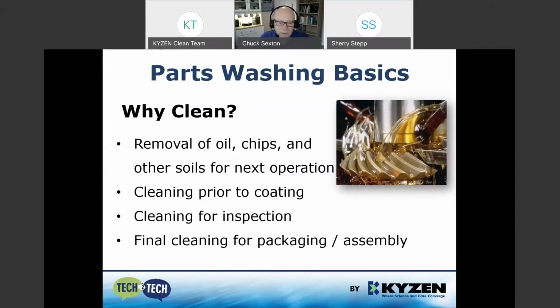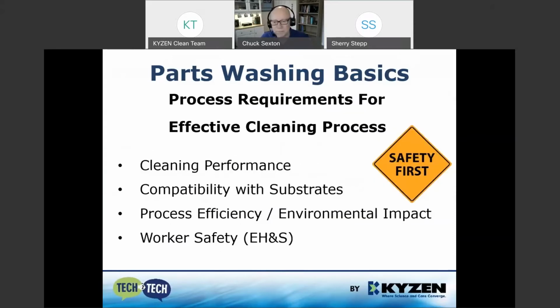Why clean? In the manufacturing world, removal of oil, chips, and other soils for the next operation. We normally call this in-process cleaning. Cleaning prior to coating, cleaning for inspection, final cleaning for packaging and assembly.